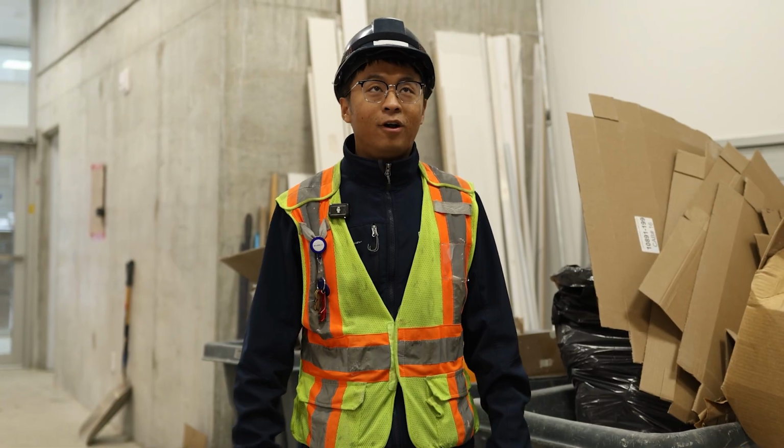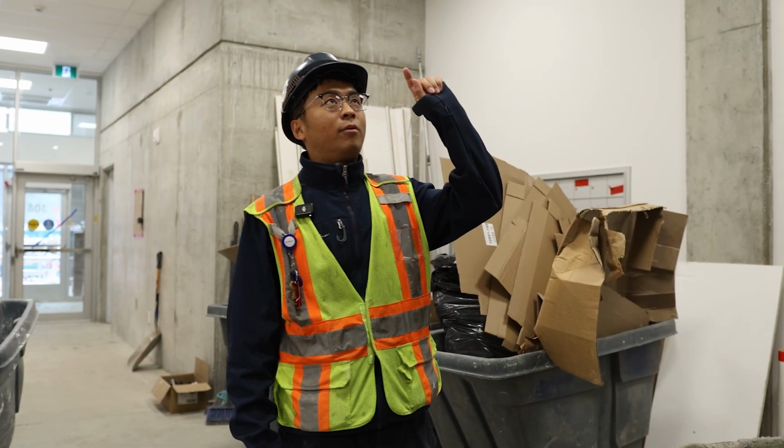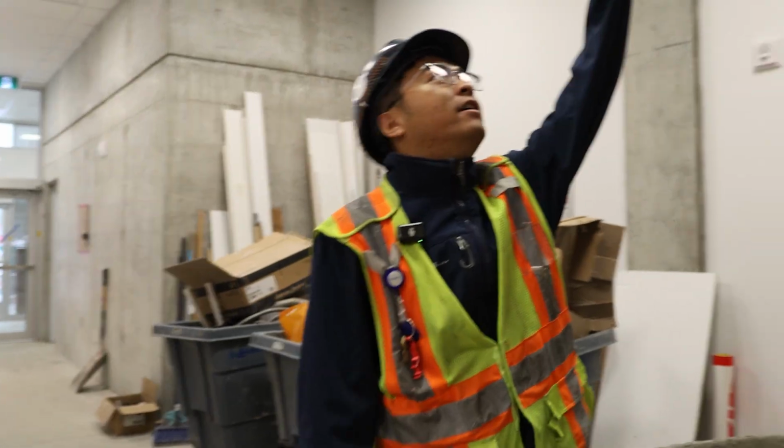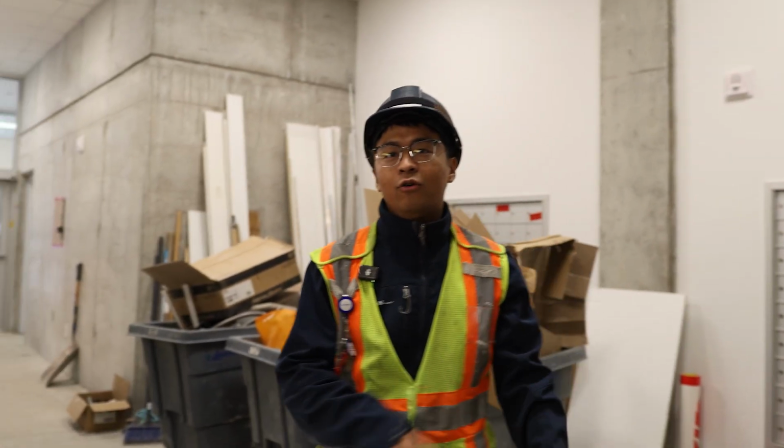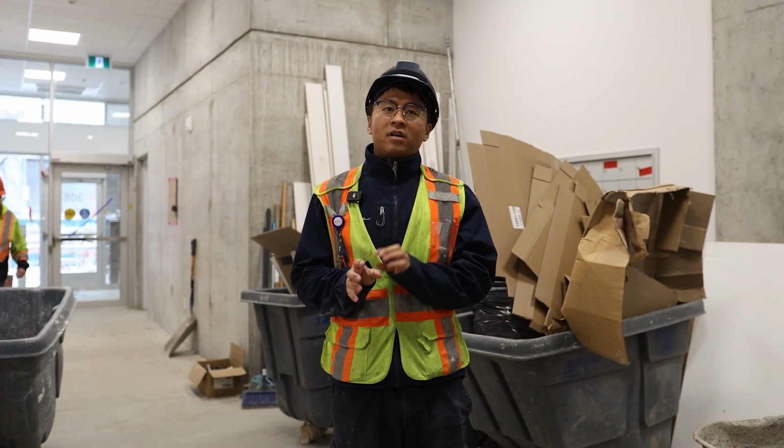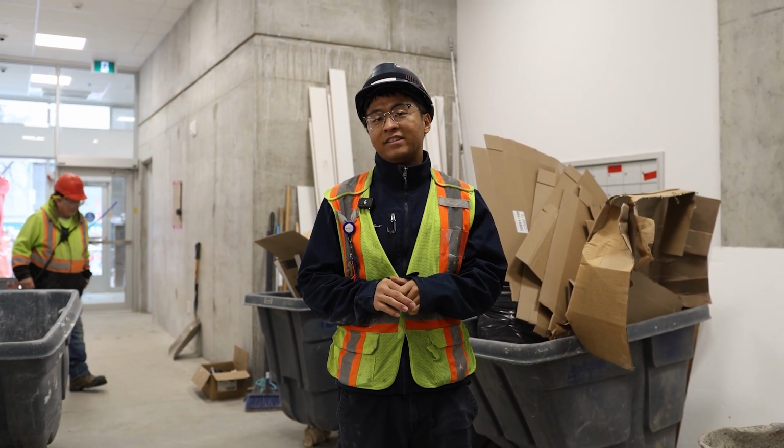Okay, welcome to the first floor lobby. So we have stairwell pressurization fan 5, just above the ceiling right here. That fan will stay running the whole time regardless. The BMS commands the fan and monitors the status of the fan.